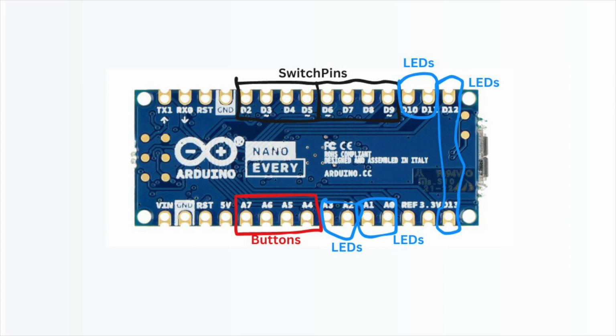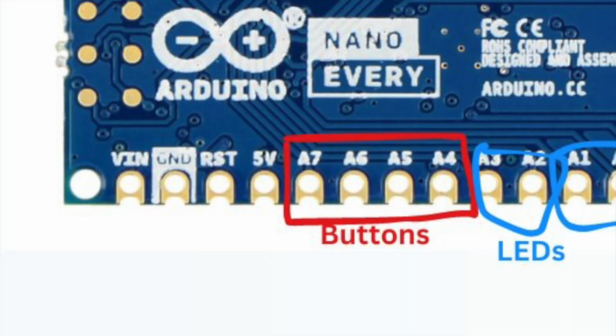2 sets of 4 leads go from the Nano, one to one of the motor controllers and one to the other motor controller. Circled in red are the button pins. The positive leg of the buttons go to these pins, along with a 1K resistor, each connected to a common ground. And that pin is only 2 locations away from the ground, which is labeled as G and D.